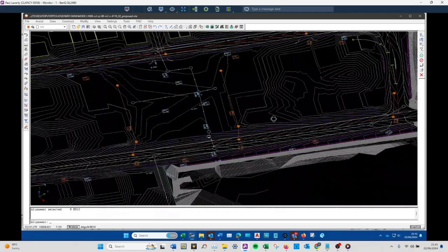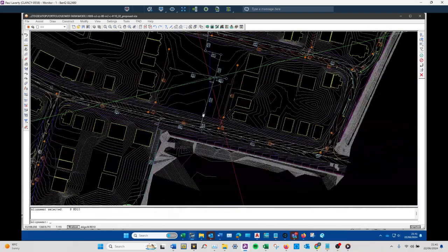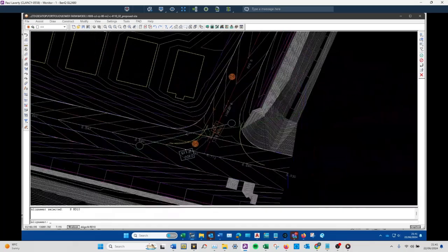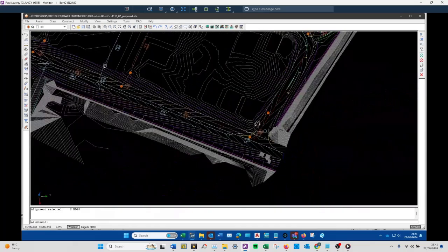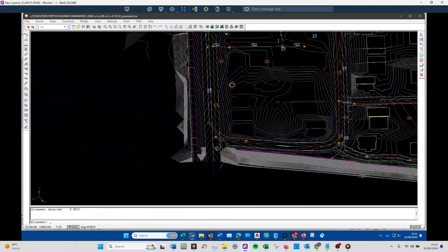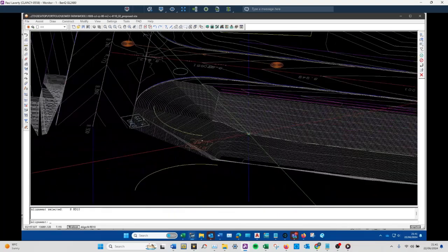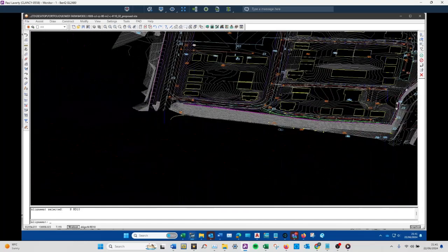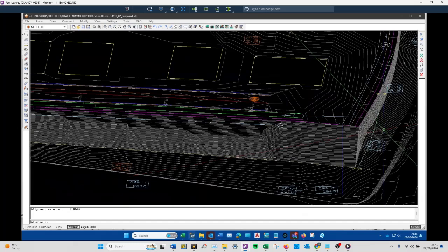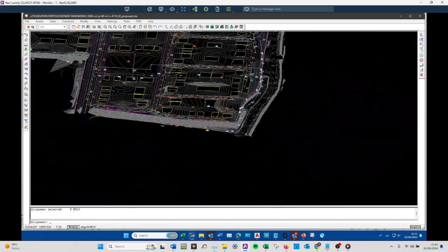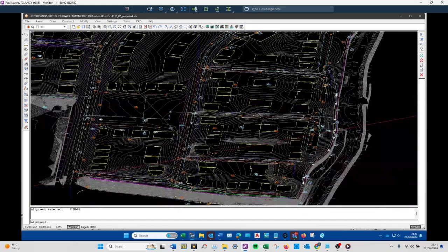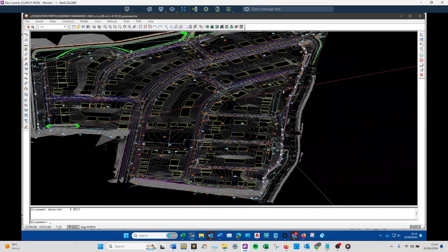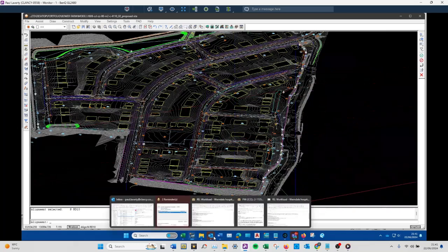And so you need to be more careful with your files in terms of not having too many layers in them. Whenever we need to edit a file to bring it into PDS, we take it and we drop it into this because we want to purge it all out for that reason. And even if you use the PDS and CAD version, it would still be good to have this folder because the architect's drawings usually have lots of hatching and coloring on them and a whole bunch of other information that's not really useful.